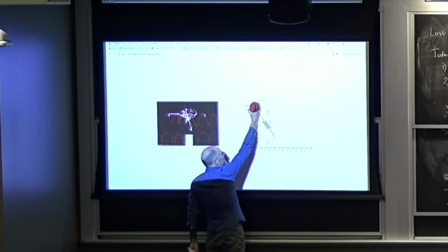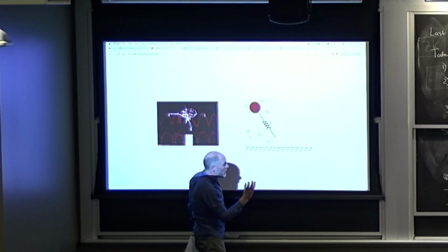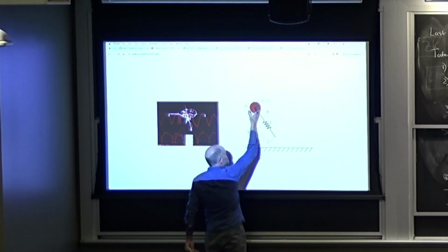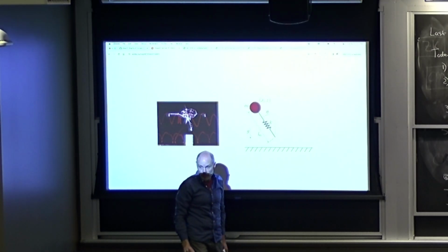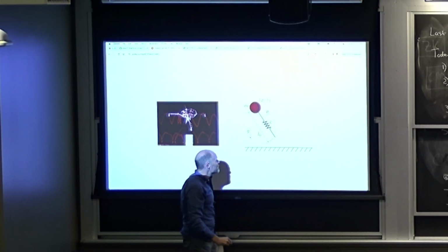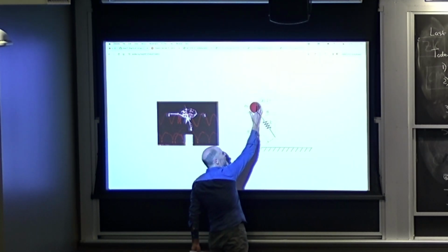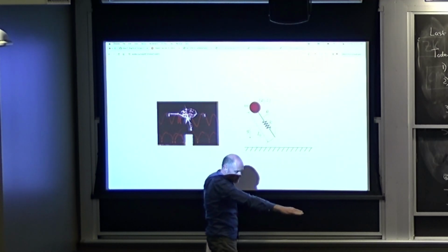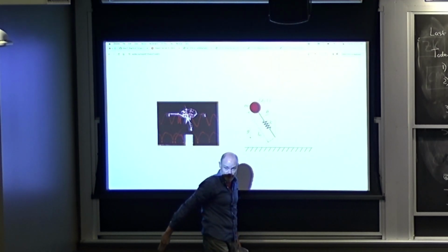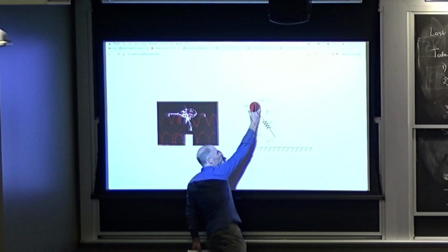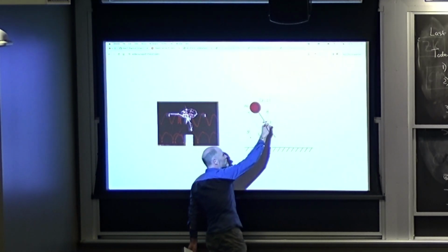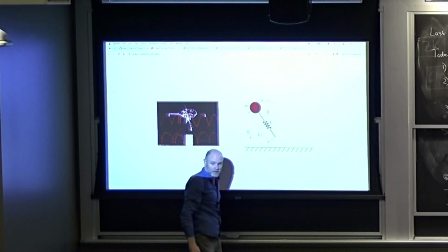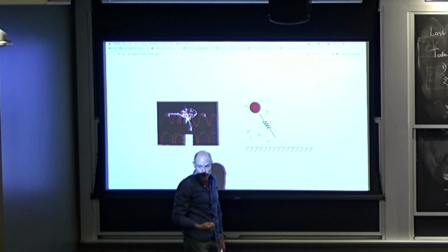It turns out, if you were to take Z, okay, and start moving the robot up and down, okay, and looking at the solution to the deadbeat controller for a particular hopping point, it turns out that as you move down, the leg sweeps through an arc smoothly. This is a little bit of a convoluted argument, but I hope you stick with it, okay? If I were to just look at from different Z's, what the optimal going to some particular nominal hopping height would do, it's going to change my leg angle smoothly. So Hartmut Geyer made this awesome observation.